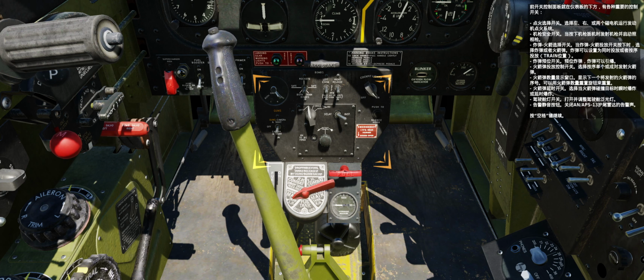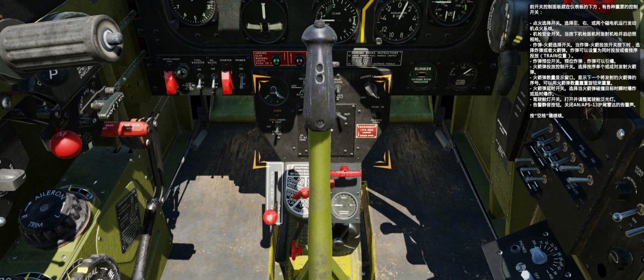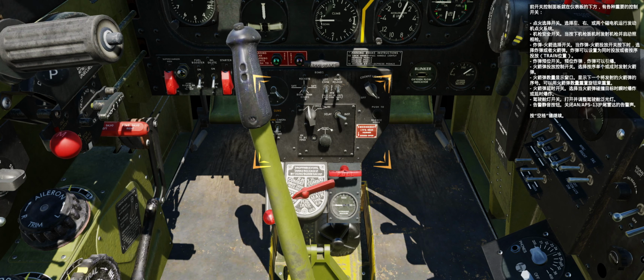Bombs can be set to release simultaneously or in sequence train. Bomb arming switches arms the bombs for detonation. Rocket release control switch selects single or ripple release of rockets in train. Rocket counter window indicates the sequential number of the next rocket to be fired. It can be reset using the rocket counter reset knob.